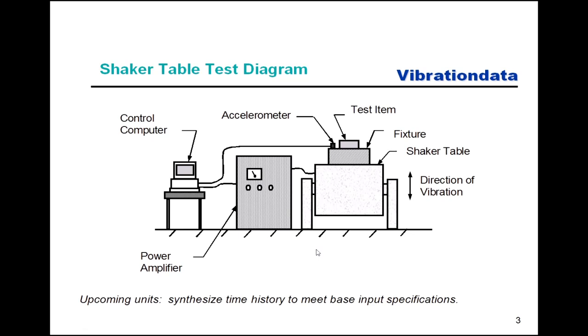Actually, the way these tests start out is that typically the control computer would put out a very, very small millivolt range signal, just to barely excite the shaker. Then it gets the response signal, and it has to calculate the transfer function and the gain factor for this loop. And that has to be a function of excitation frequency.